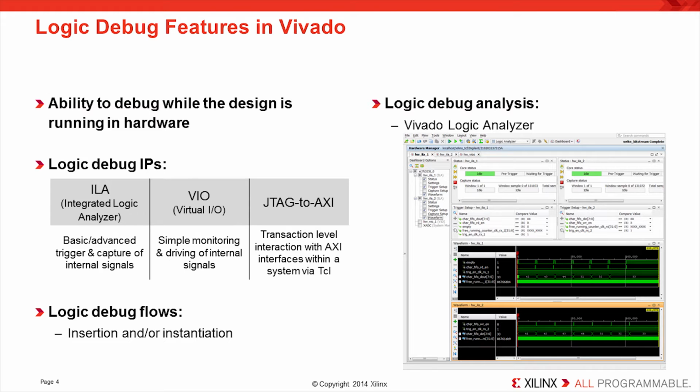Once debug IPs are added and implemented in your design, you use Vivado Logic Analyzer to interact with Logic Debug IPs. Logic Analyzer provides you with an easy setup for taking measurements and capturing data using customizable dashboards. You can also analyze the captured data through a configurable waveform viewer. Now let's find out how we enable your design for Logic Debug.